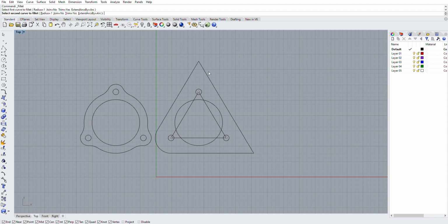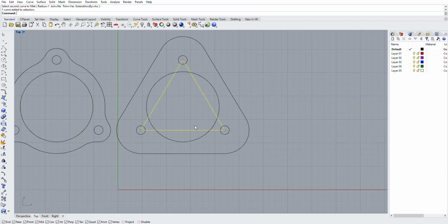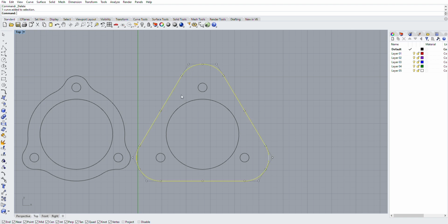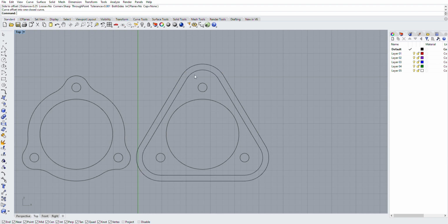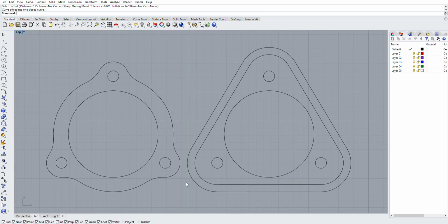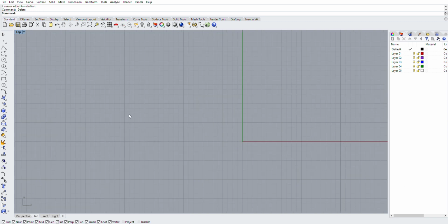You can see how at any point around that bolt hole, it has the exact same amount of meat all the way around it on the outside. And I mean, that's two different ways to build a flange, two different aesthetics. They both work. And if you don't like how beefy that is, we just grab the outer ring, click offset again, and pull it in. And just like that, I can offset it a 1/4 inch, and it's a completely different bracket with a 5-second command. Super handy.